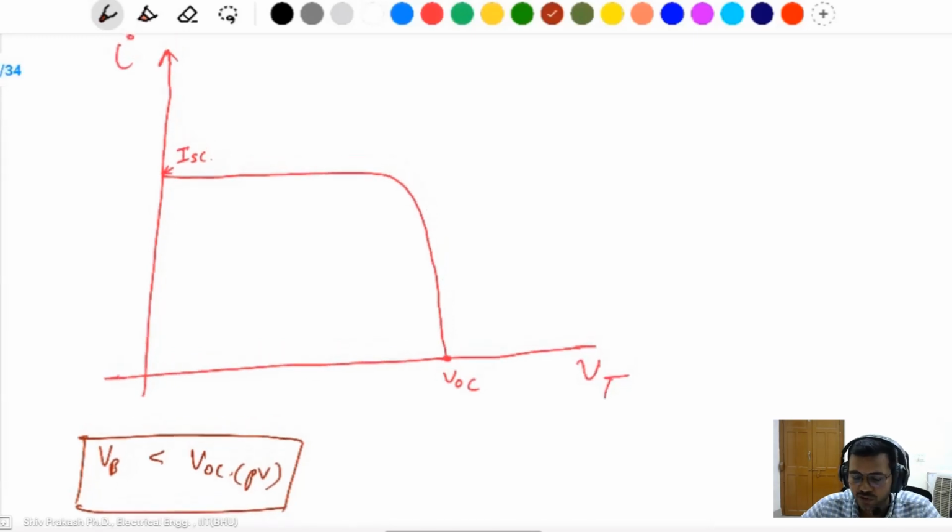Then with respect to that voltage, current will flow from the solar panel according to the insolation. So if you have some battery voltage, at the PV terminal there is the rated nominal voltage like that. But if you charge this one, the terminal voltage of the battery will increase because of the internal resistance.